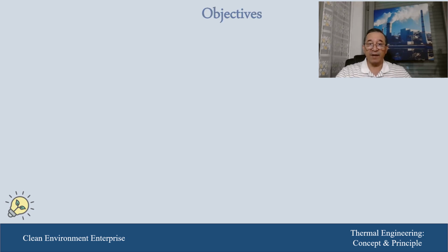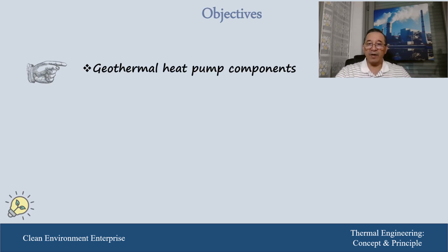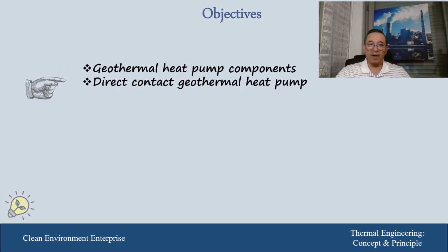The objectives of the present episode are related to the geothermal heat pump components and a full description of these components and their layout with the geothermal heat exchanger, and then we will go to the direct contact geothermal heat pump, which includes the heat exchanger called the DX geothermal heat exchanger, where the same fluid that is circulated through the heat pump is also passed through the geothermal heat exchanger.